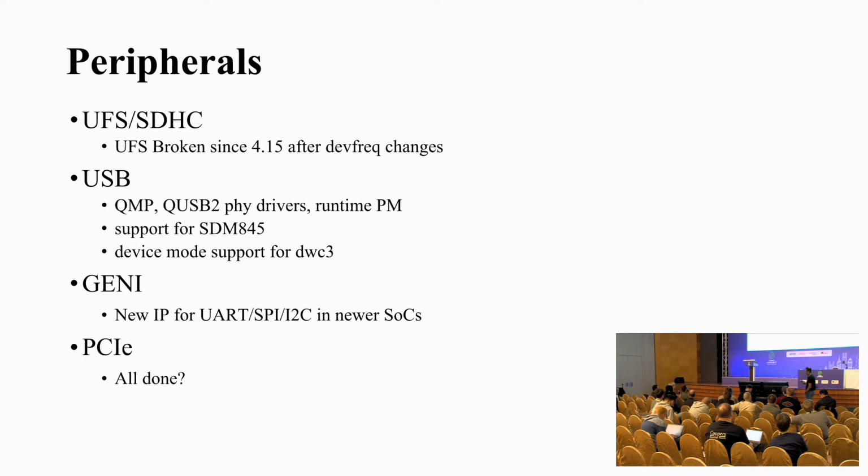So the lane clocks come from the PHY, but 50% of the time, the PHY initialization ends somewhat later, typically because of probe defer from the regulators, and that causes the lane clock not to turn on. I've done some debugging and talked to Vivek about it, and we need to figure out what that is, and we don't know if we will have that on, for example, 845 as well, or if it's something specific to 820. I think the 845 support patches haven't started flowing in yet. No, I haven't seen anything there.